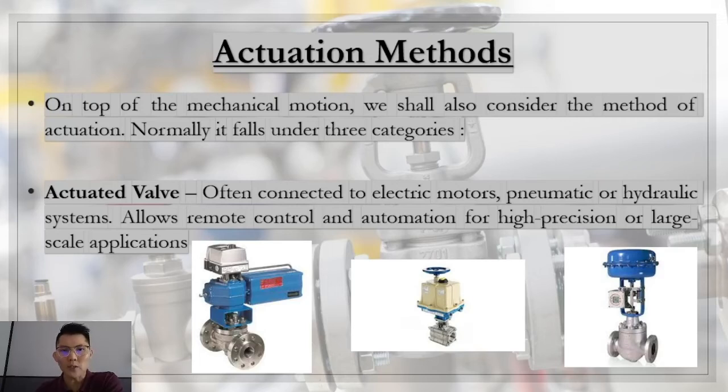This depends on the application engineer and their study of the torque curve of the valve, because a ball valve and a butterfly valve will have different torque curves. So there are different suitabilities between the different types of actuator and different types of valve. So how can they be used or coupled together? On Jaja Razin's comment, some valves have both a gearbox and an actuator.